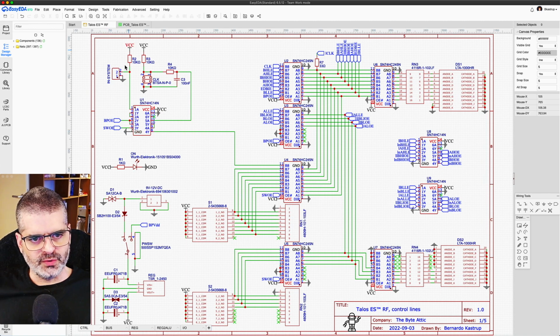This is the circuitry for generating a local clock pulse by pressing a button on the board. In other words, standalone mode, not in system. So there is this push button here, which if you don't press it, it's closed. So when it's closed, this potential here, ground, will be on the top, and therefore this capacitor will discharge to ground, and this value will be a logic 0, which goes into a Schmitt trigger inverter.